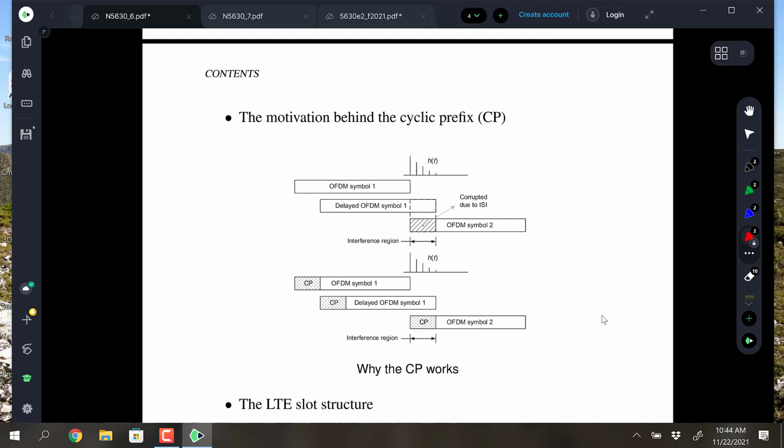I'm passionate about that because I had this student who did her dissertation with something for OFDM. I should remember exactly what she did, but she had some really novel intercarrier interference study. That's another thing that happens with OFDM, because when you're in motion, everything gets Doppler, right? So when you're in motion, the carriers bleed into each other and you get what's called ICI, intercarrier interference, and you can estimate that away with some algorithms. And she had a novel approach that would do it iteratively that she developed for her dissertation.